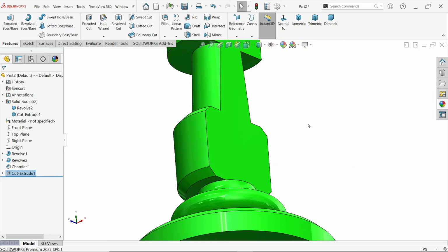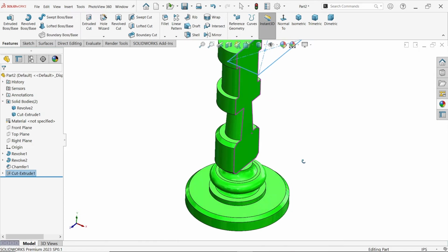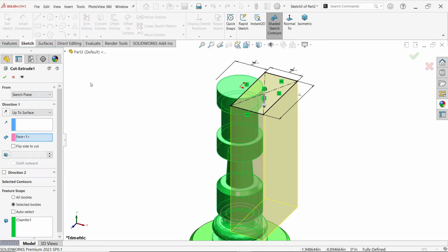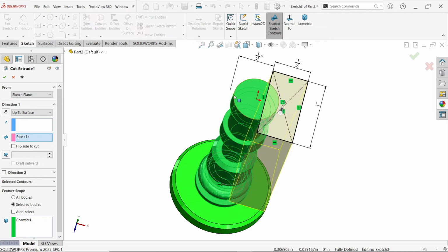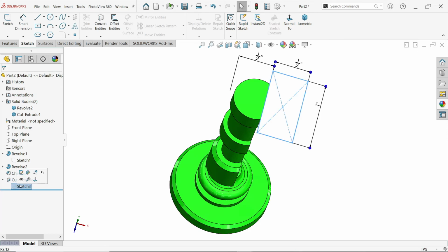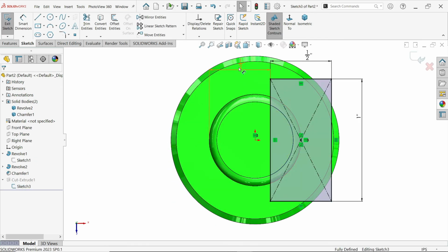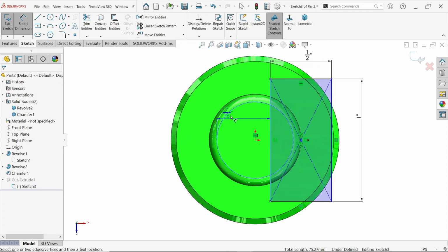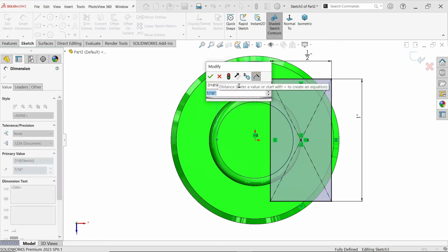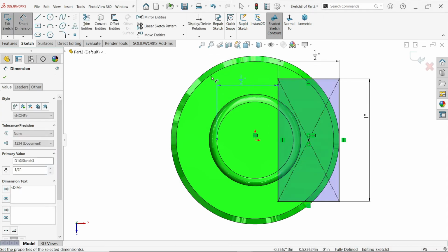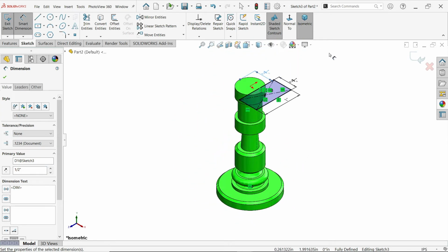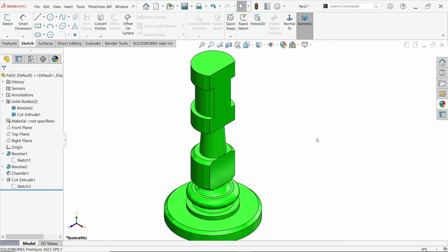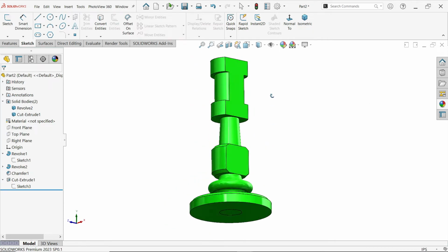Okay. Look. Now here we miss dimension. It should be from here 1 point, not from this outer face. So simply exit sketch, and delete this dimension from this. Hold shift key, then make dimension from here, and this is going to be 1.2 inch. Okay. Say okay. See.